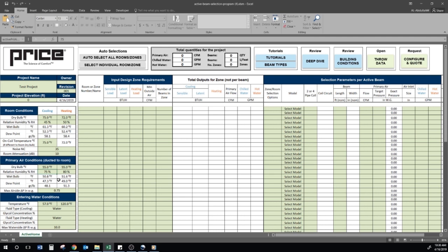We also have the option to limit the static pressure buildup at each chilled beam. Typical selections are done between 0.2 to 0.8 inches of static pressure. Below 0.2, we run the risk of losing induction at the chilled beam. Above 0.8, it becomes a balancing act between high static pressure buildup and noise.